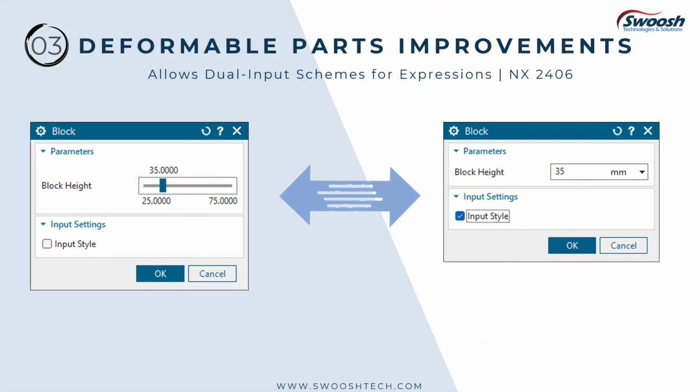In NX 2406, you can now add multiple widgets to control the same expression in different ways, and these will automatically stay synchronized. This can be useful in creating a dialog design with simple and advanced concepts by coupling a slider and a direct key-in entry. You also have the ability to toggle the visibility of those inputs.